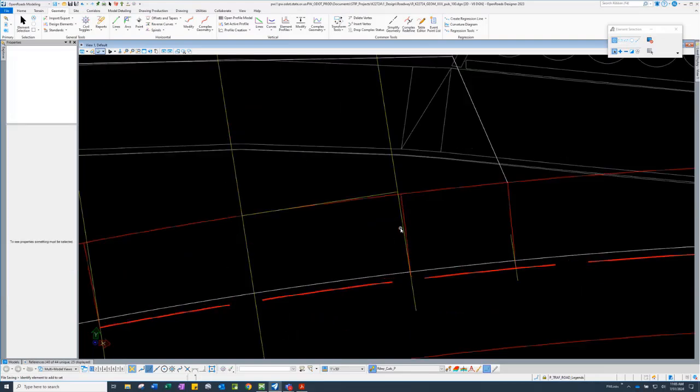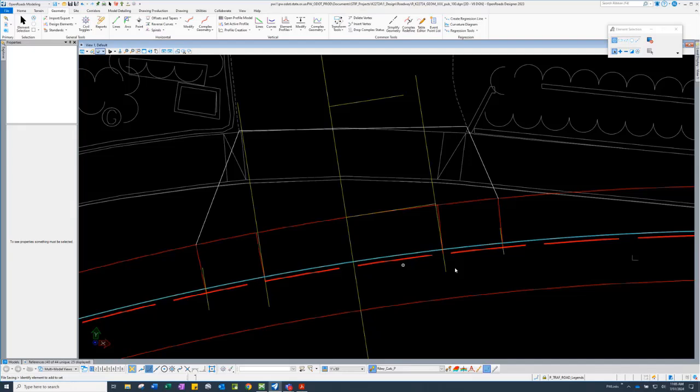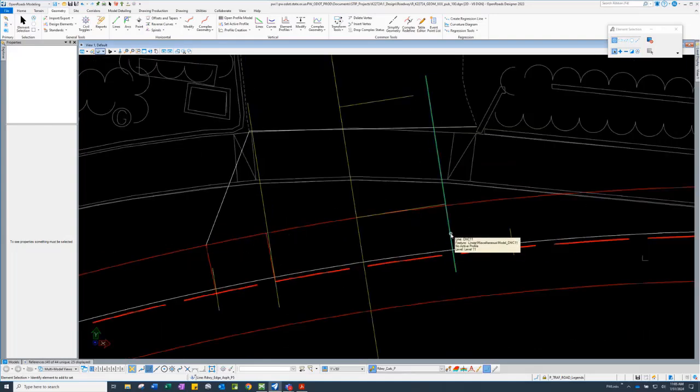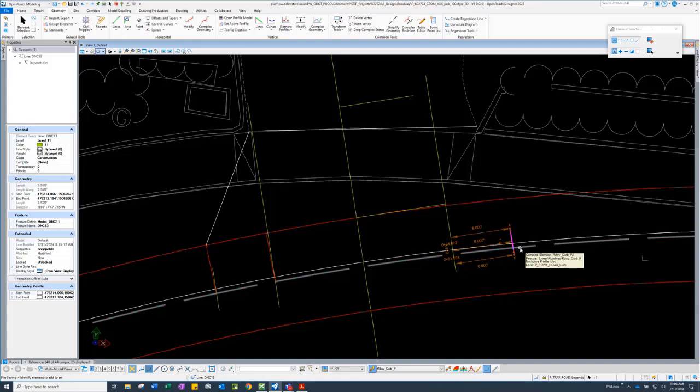Now, when I started looking at it, you'll realize that it's not perpendicular to the alignment. And so this is where, and Lenny, you want me to redraw these lines, right? Yes, I do want you to redraw the right-hand side. Perfect. Okay. So just to show people how we did exactly. So to do that, I still use the same partial offset of 12, and I did a partial offset of 8 for the wing or the ramp, however you want to call it, of the driveway.